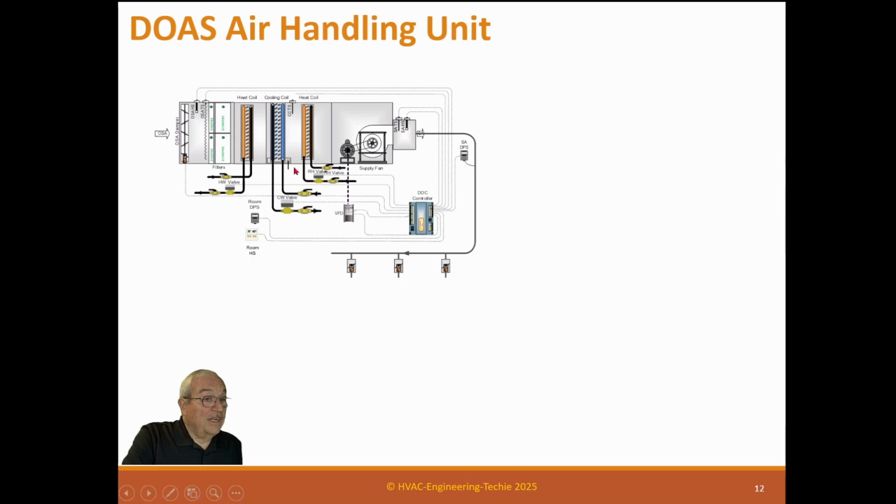So if you can just provide it one time and these units don't have to do that, then your job gets less expensive. And also, this is a high maintenance issue. So you have one unit you have to spend more maintenance on than these. So that also reduces your cost because you have a single point of doing it. And that's why DOASs work and are popular.